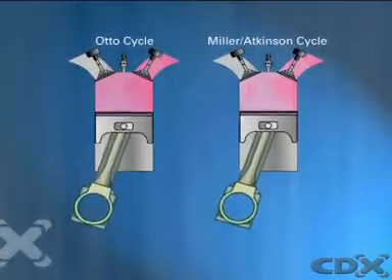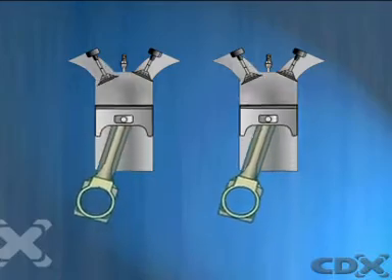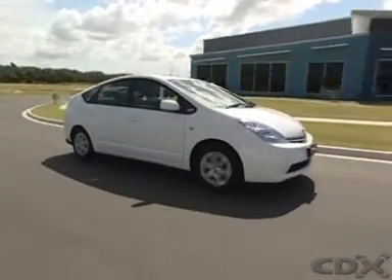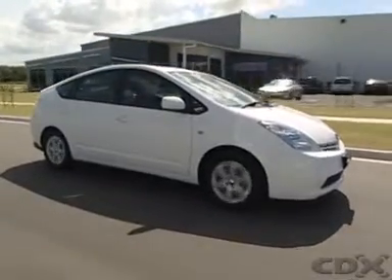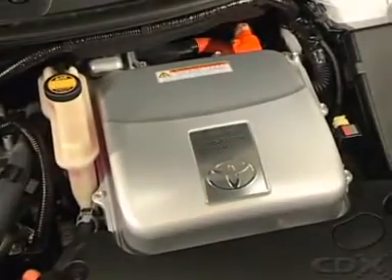The Atkinson cycle engine is efficient within a specific operating range, typically between 2000 and 4500 rpm, but its power output and torque are lower than a conventional engine. This type of engine is less useful as a primary power source, but is ideal in applications such as a series parallel hybrid vehicle, charging and working in tandem with a battery-driven electric motor.